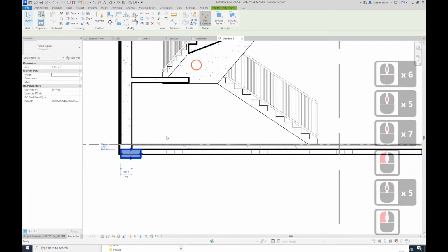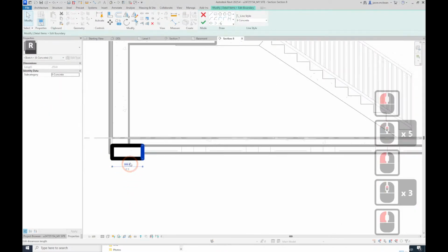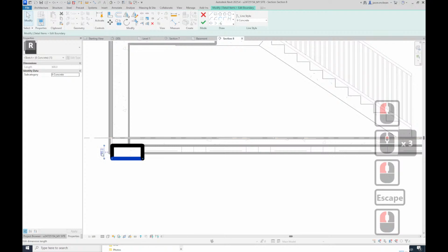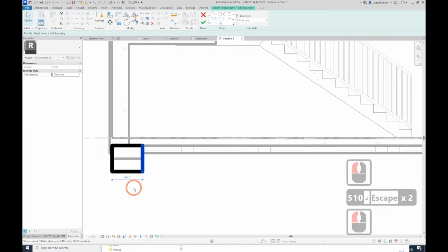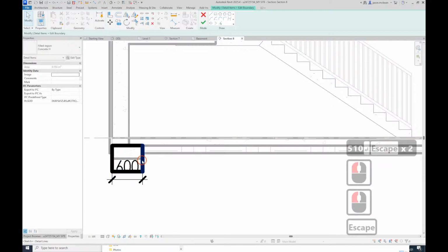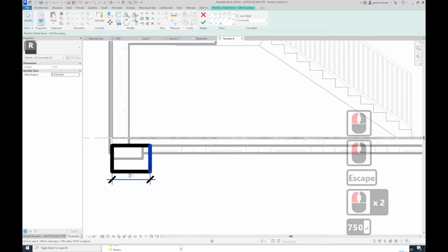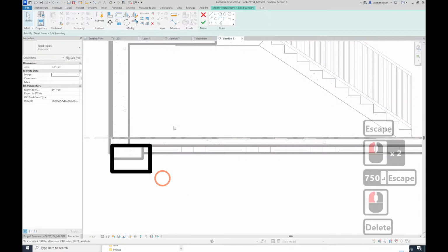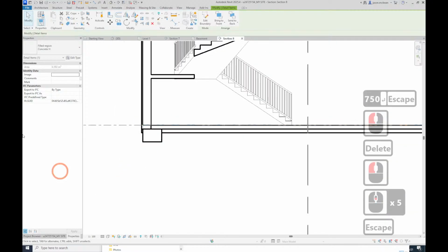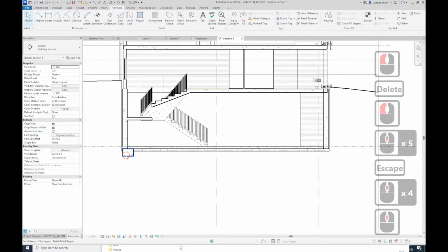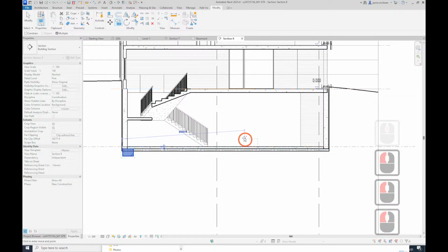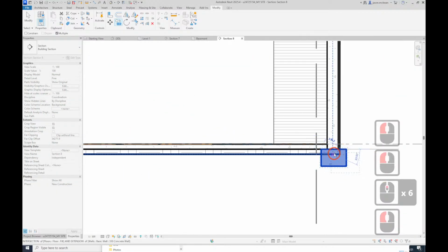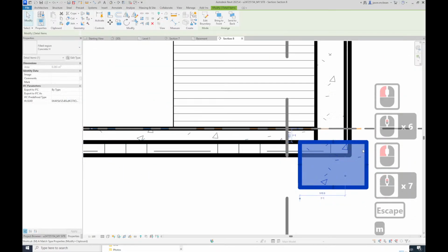Something's not quite right there, edit. Let's go check something. That should be 600. You can make that 510, so it's like a ground beam maybe. And maybe make that 750. Then it's more, sorry, don't do that. You can leave them in, they're never visible because they're just draft, they're right there. But you make one, you can make this a group and you move it everywhere. So now you just copy this guy. It's so quick when you draft in Revit, once you know what you're doing. So that goes there, I'm going to move it again, MV, move.